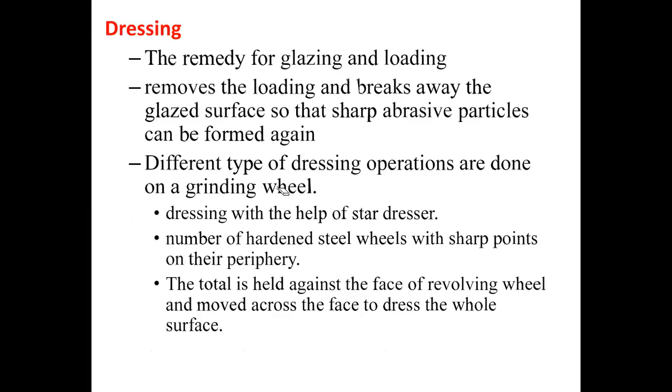In addition, there are a few more defects. To overcome these defects, you need to do the dressing. So grinding wheel dressing is required. It is the remedy for glazing and loading. What we do in dressing is remove the loading and break away the glazed surface so that sharp abrasive particles can be formed again.